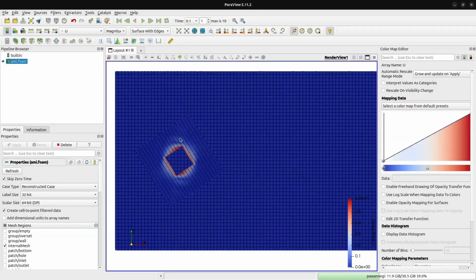We want to create a mesh interface which is of circular shape such that we can have a rotatory zone in the middle, and along the circular interface we want a mesh interface where we want to perform the interpolation that has better accuracy compared to an overset mesh. Wherever we can have an arbitrary mesh interface like a sliding mesh or a rotating mesh, we should prefer that over overset mesh. Let's get started.